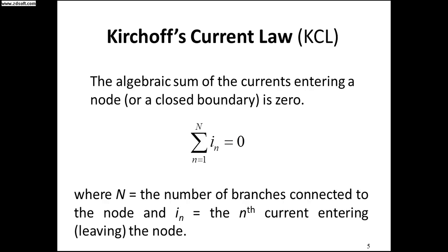Next one is Kirchhoff's law. Kirchhoff's law is of two types. One is Kirchhoff's current law, the next one is Kirchhoff's voltage law. Kirchhoff's current law states that the algebraic sum of the current entering a node is equal to the sum of the current leaving the node.